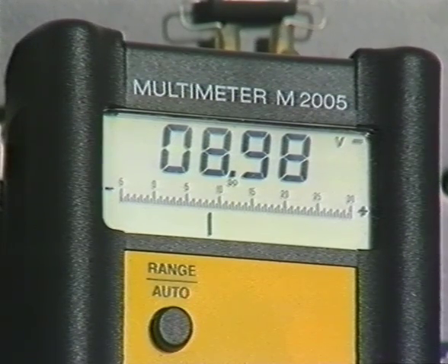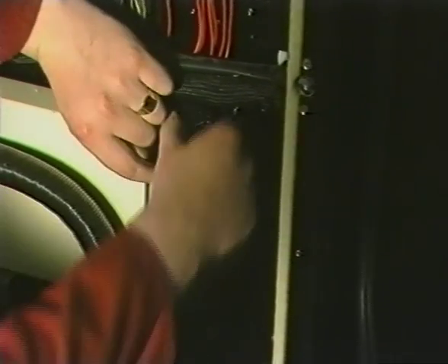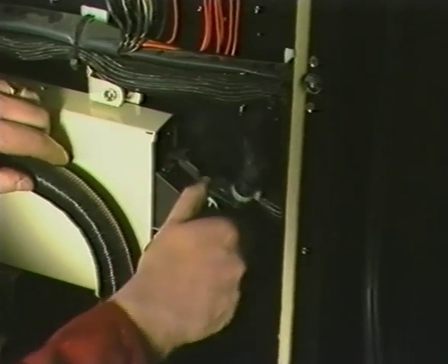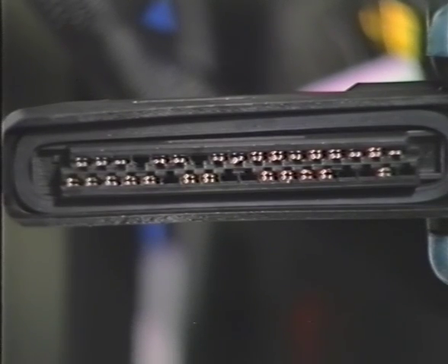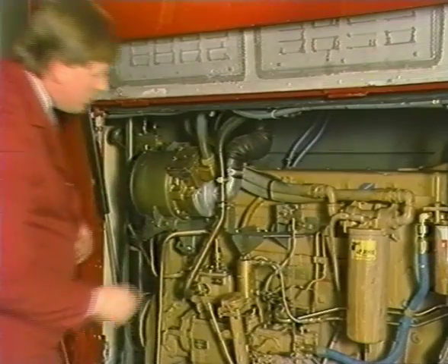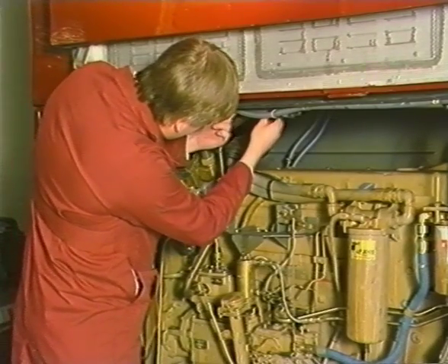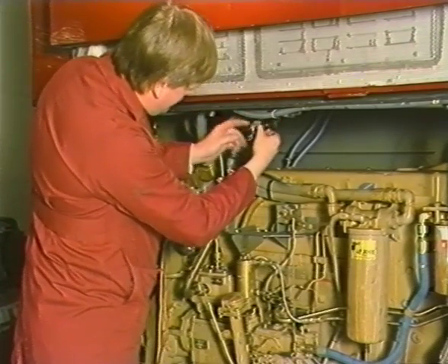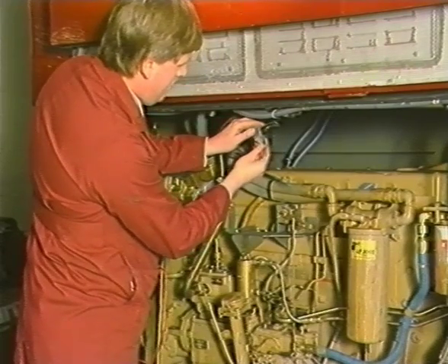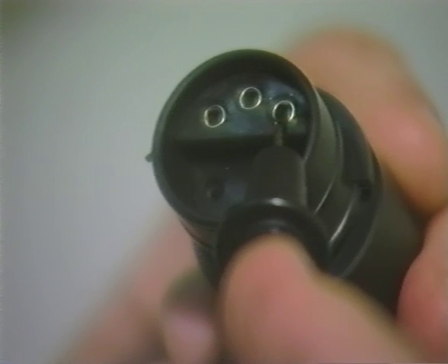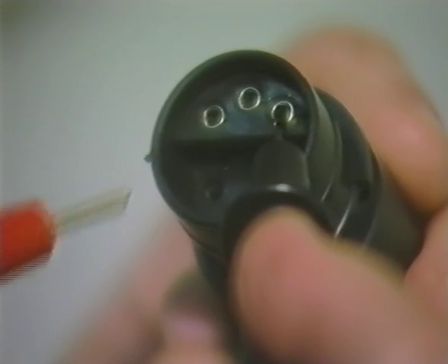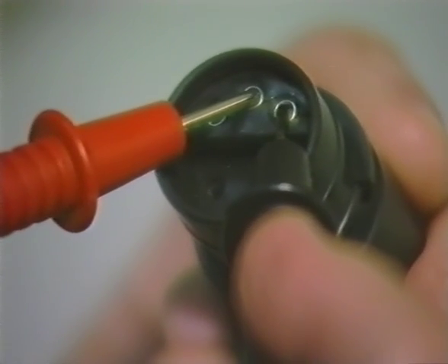If correct, check the resistance of the load sender at terminals 16 and 35 on the panel plug, and the reading should vary between 1000 ohms and 400 ohms between idle and full throttle. If there is no reading, before replacing the load sender, check the resistance reading at the Cannon connector. Should there be a reading, there is a cable fault between the load sender and the panel.